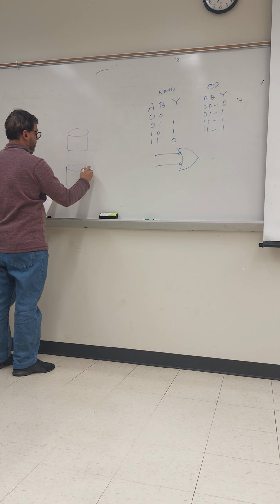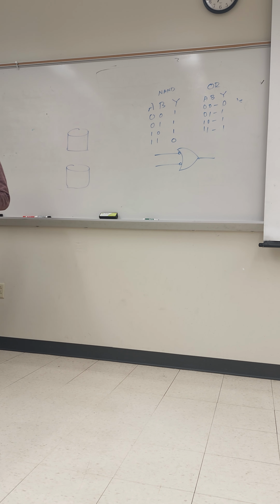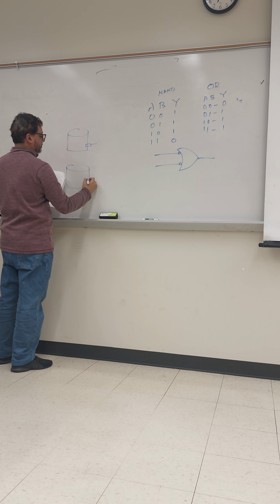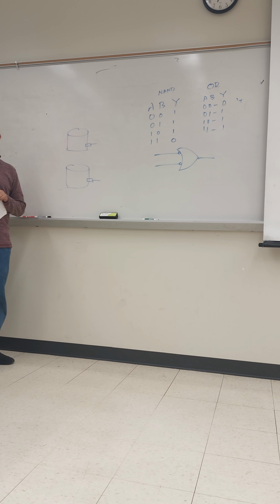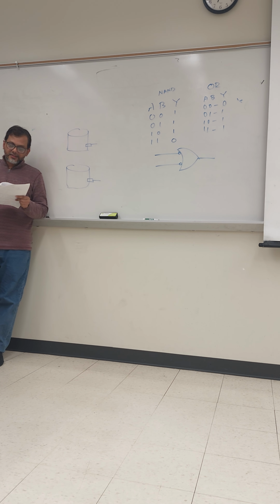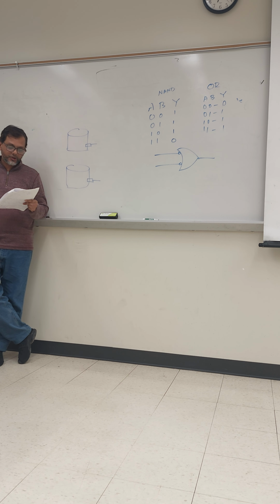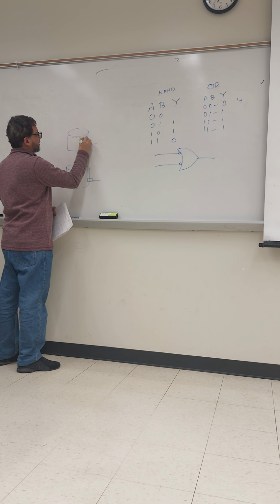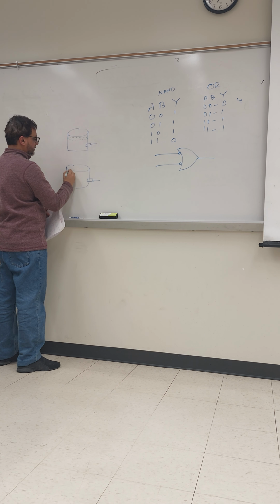The first thing they said is that each tank has a sensor. For example, if I draw a sensor here, this is a sensor, and it detects when the chemical level drops to 25% of full. The sensor produces a high level of 5 volt when the tanks are more than 1 quarter full. So it is high when they are okay. When they are full, they will create, for example, this high level.